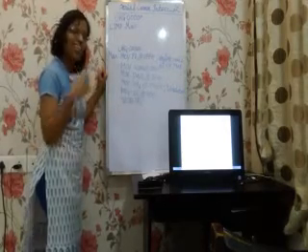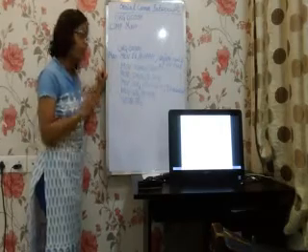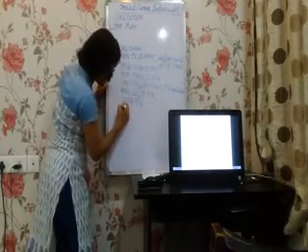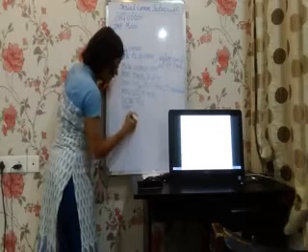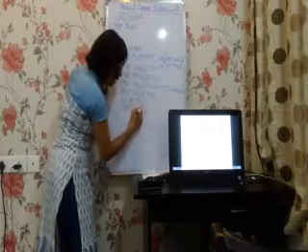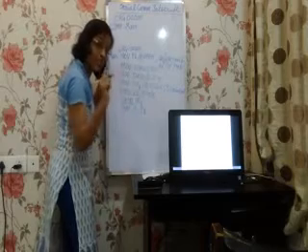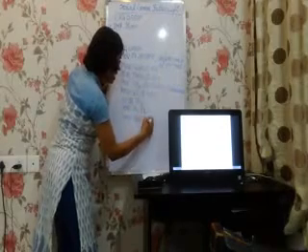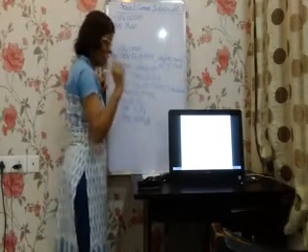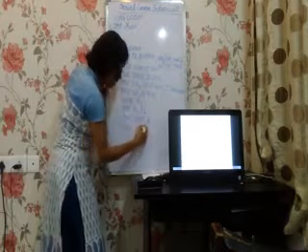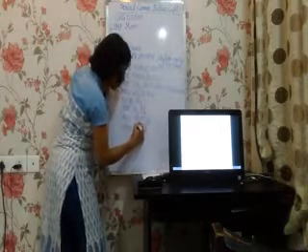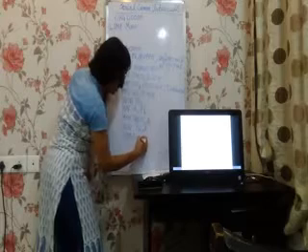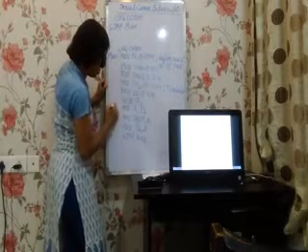Till the time the flag is raised, we have to send the data from port 1 to port 2, and from port 2 to the serial communication port. So I move the data from port 1 to the accumulator. From the accumulator I send it to the serial communication port by putting it in the SBUF register: MOV SBUF, A. Also give a copy from the accumulator to port 2. And this you have to do continuously, so I give SJMP back, and the back label goes over here.